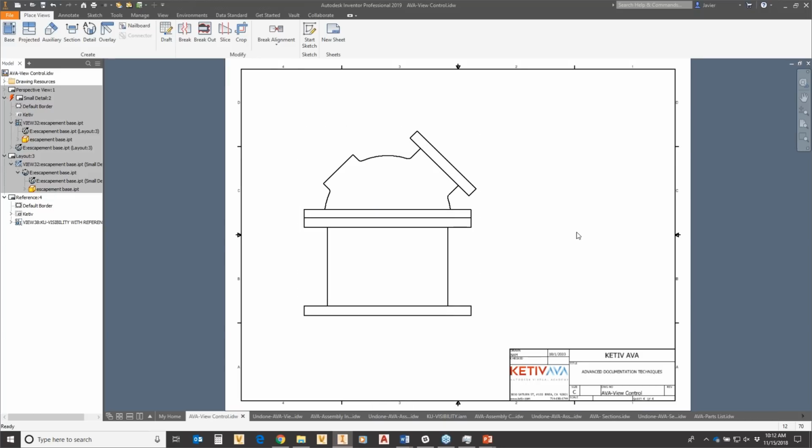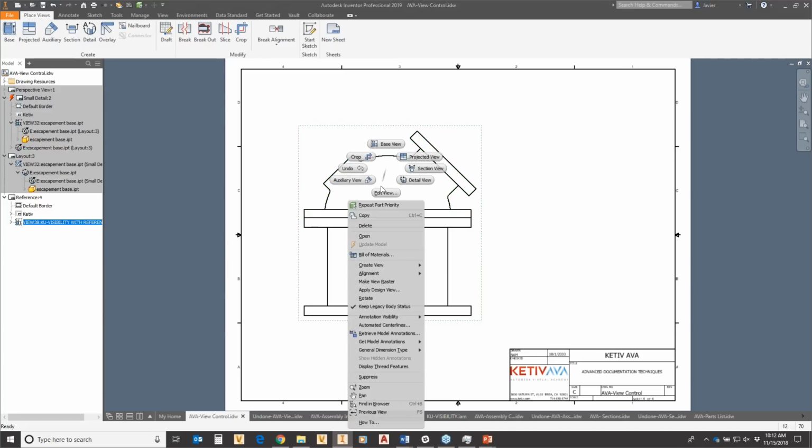So make sure that when you're working with your drawings, you shift right click so that you pick what it is you want. In this case, I want to pick parts. Now I've picked the part, and because I've picked a part, I've got part options, right? So a number of things we could do. We can certainly suppress it. We can show it in a number of ways.